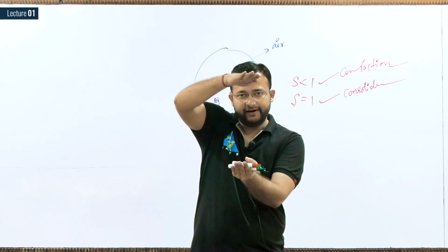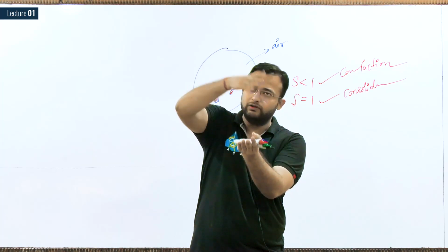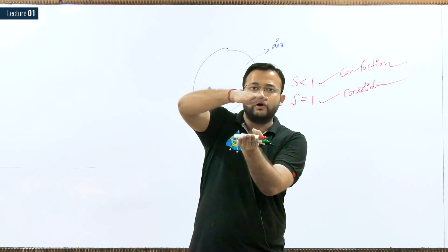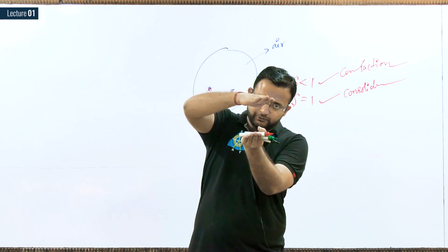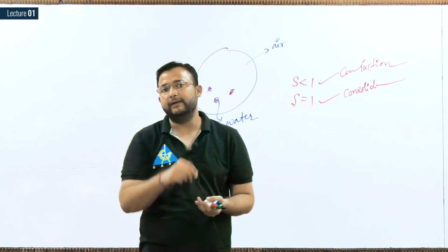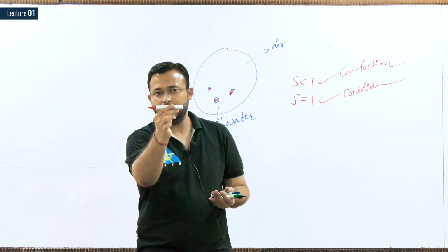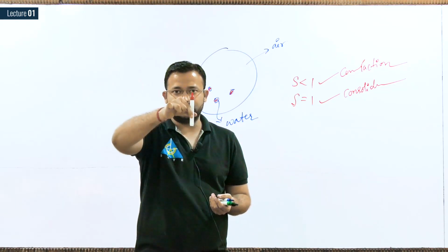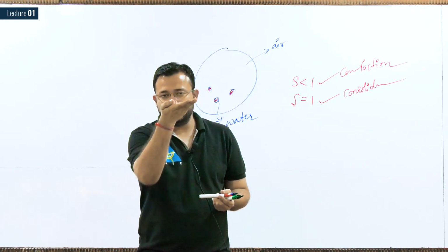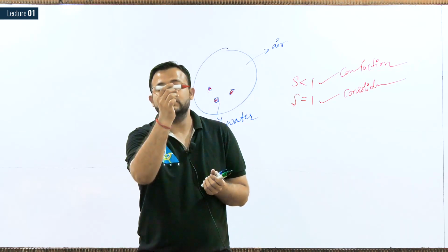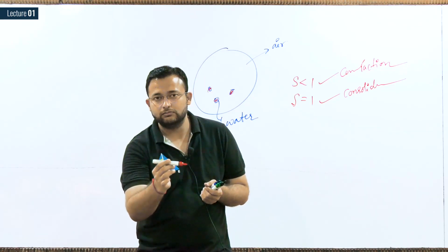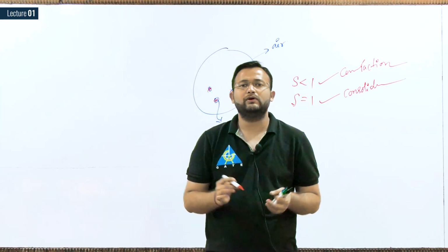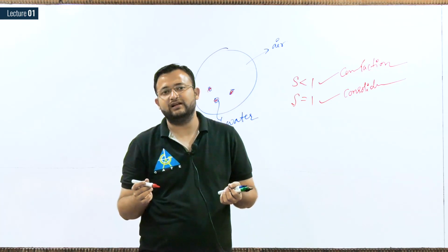There is a reduction in the volume of soil. Because of the self weight of the structure, the volume of soil is reducing, and on the soil I kept my footing. This is the footing, and on this footing the structure is present, and below the base of the footing we have soil. If the soil is getting settled, then the footing will get settled. Okay. So what will happen, sir, if the footing is getting settlement?